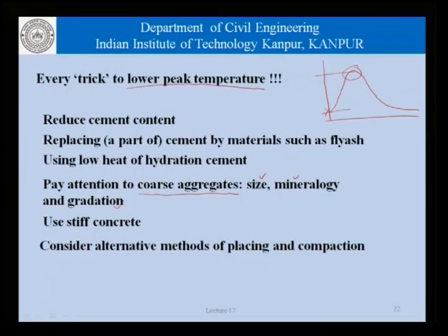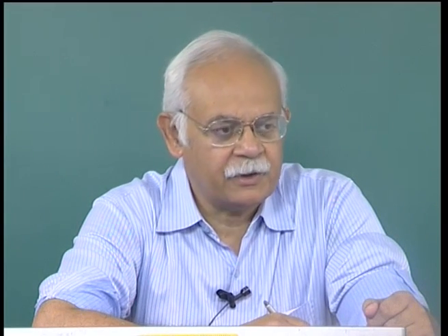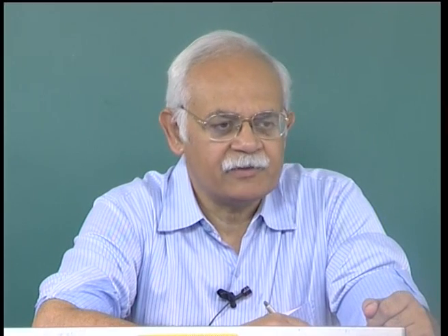We should use as stiff a concrete as possible, because if we use stiff concrete, basically what we do is reduce the water content, and if we reduce the water content, by simple arithmetic, we reduce the cement content, and that contributes to the reduction in the amount of heat that is generated.